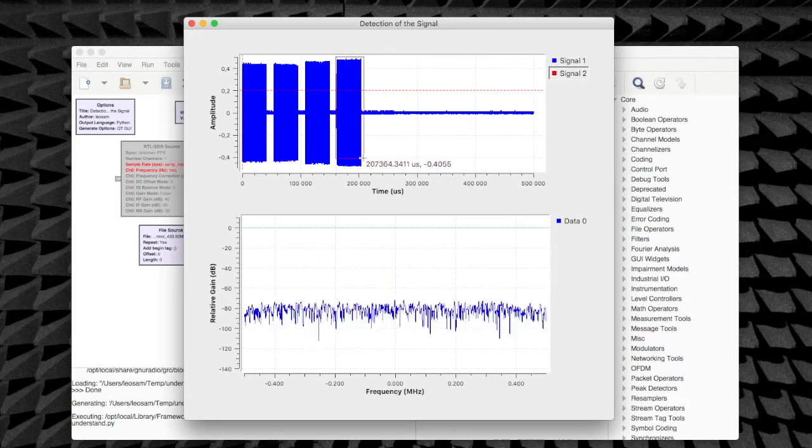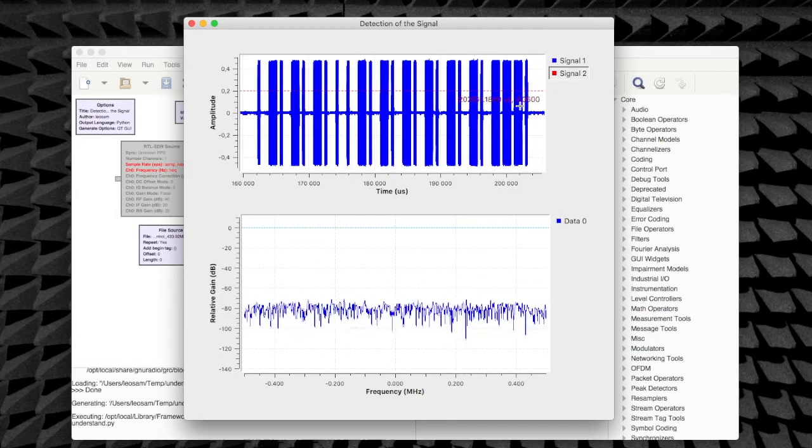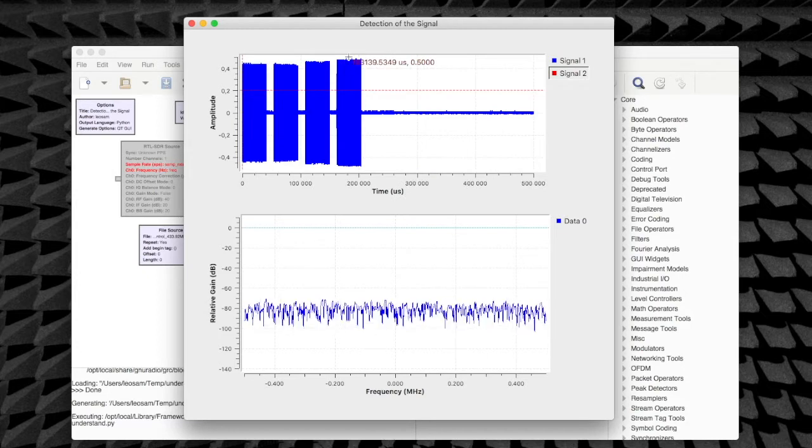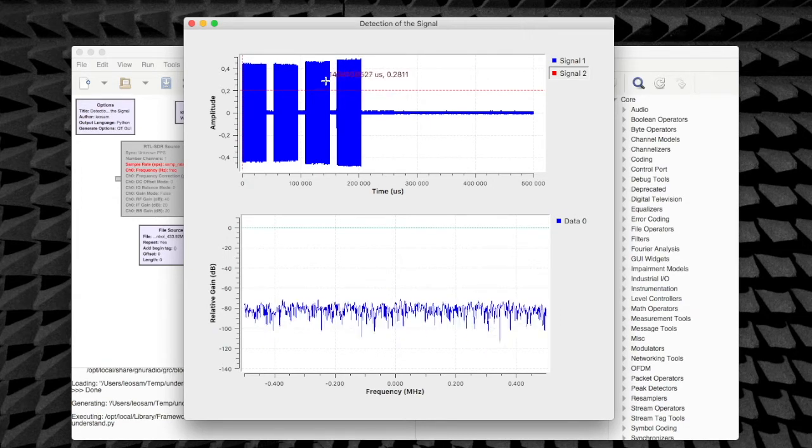And then fourth one, we have thick, thick, and thin, which makes us think that this is also something which is changing from the two first ones to the two last ones, so that it might also contain a part of the information about what to do when the button is pressed. You notice that for all of the four, the last one was a thin one, and that might indicate an end of frame or end of packet kind of a flag that indicates to the receiver that it can stop listening at this point.